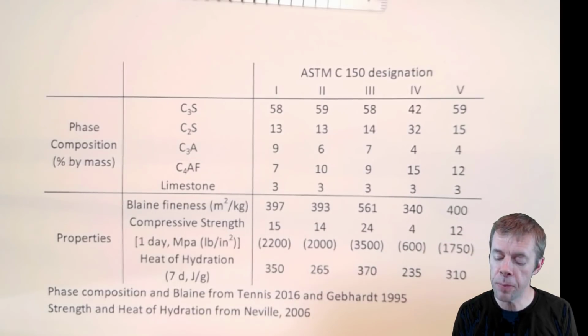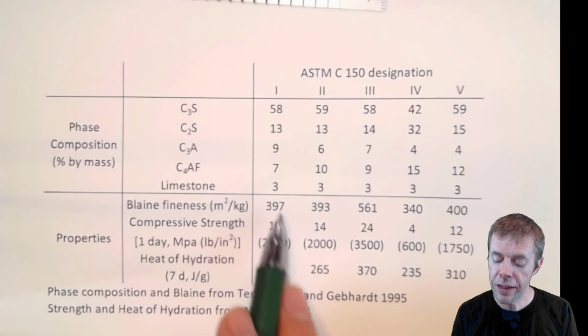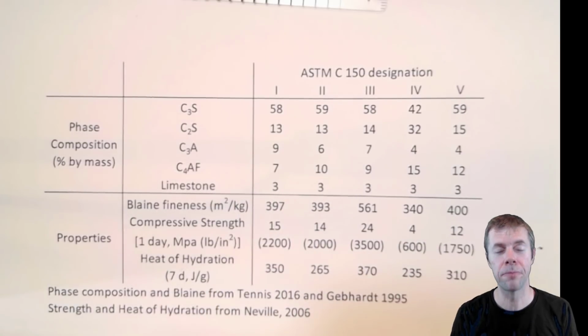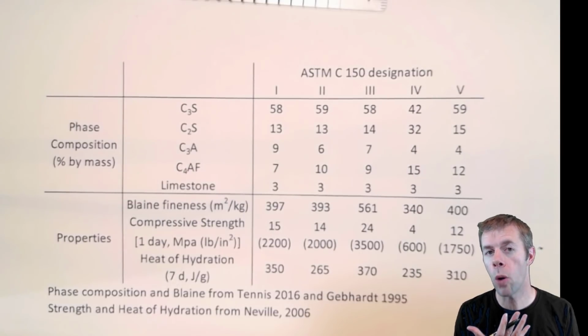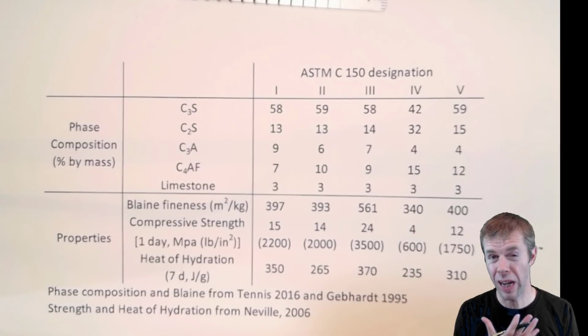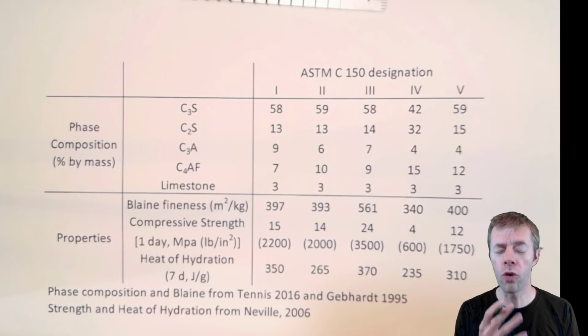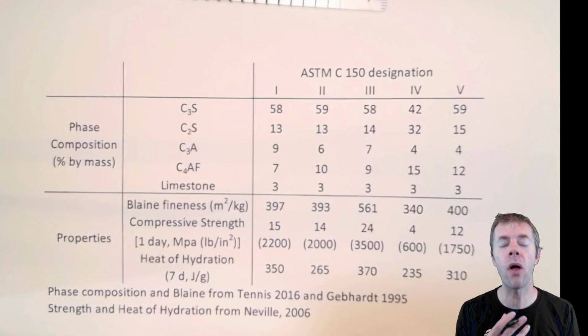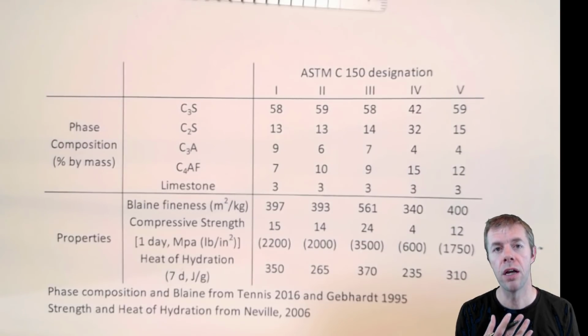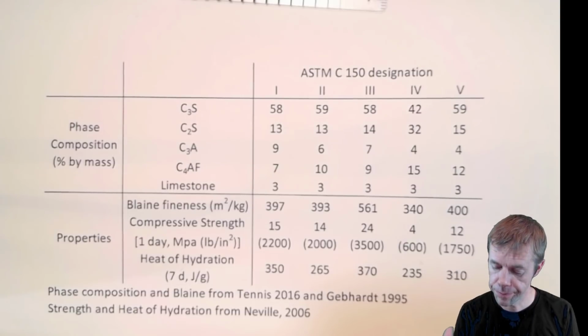You'll also notice that as people started to add limestone, these Blaine numbers have gone up. That means they're having to grind their cement finer, on average, to overcome the not as reactive limestone particles, or because the grinding is just different with those softer limestone materials being added.